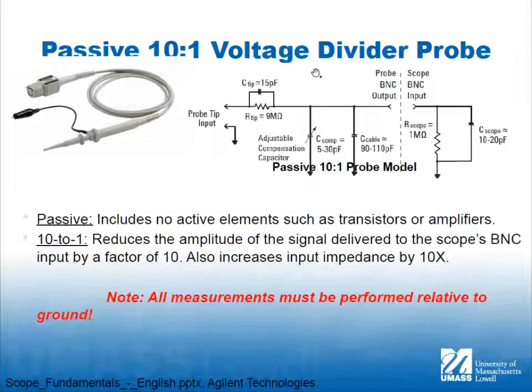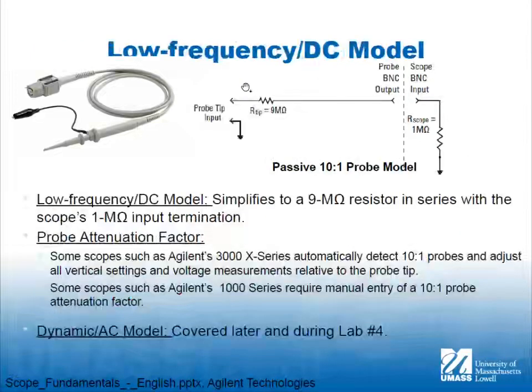Remember that the cable on this probe is probably 1 meter long, and a meter is in the range of 5 nanoseconds. So there's that much delay in the signal just to get to the instrument. So lots of problems making these connections.